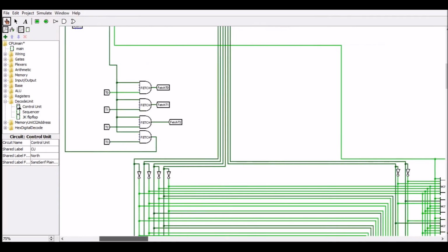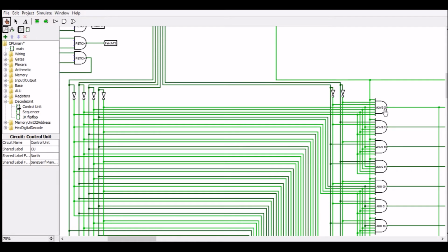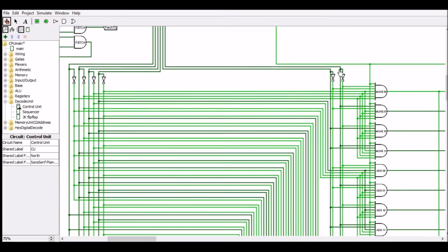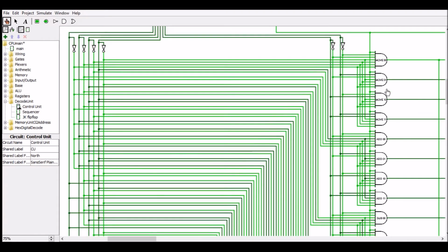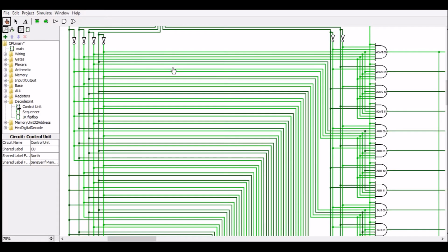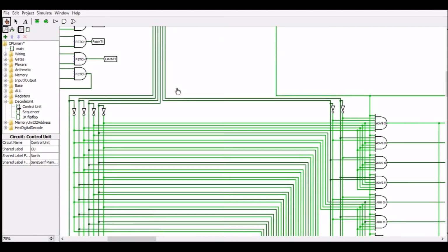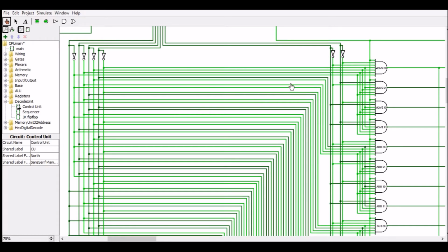The execute phase then enables these gates to be true. So this is simple decoding logic, like in the big decoder that was used. It decodes the addressing mode and the opcode being used. But before we get into this, we should probably look at the architecture of the instruction to see how instructions are made up.